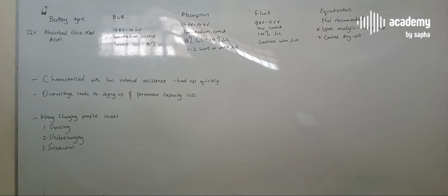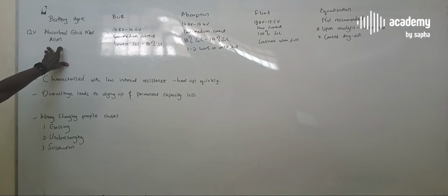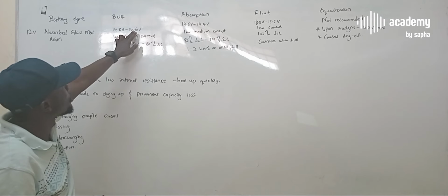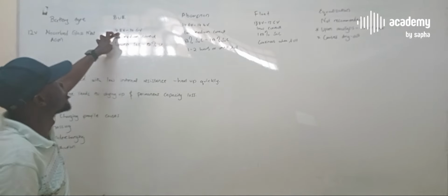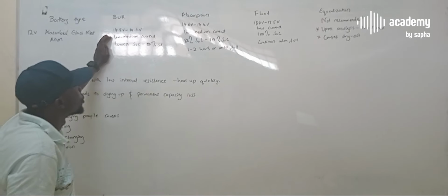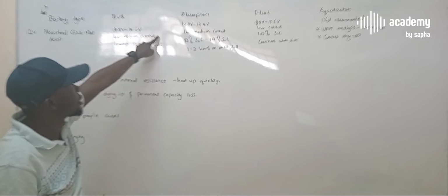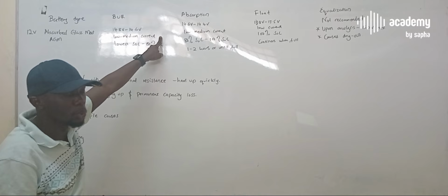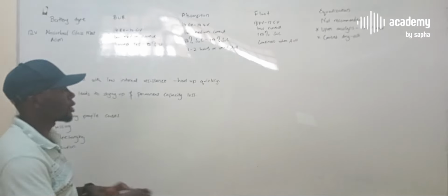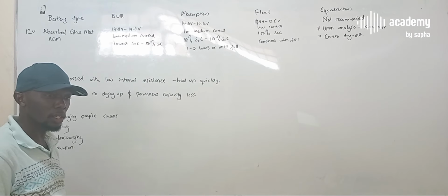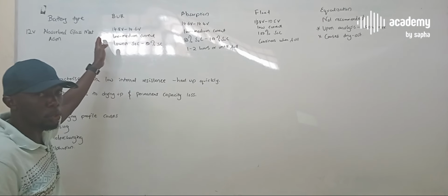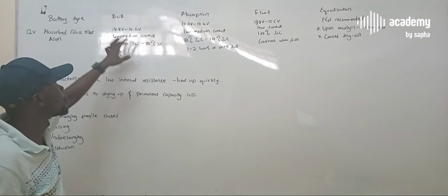So the second type of battery is the absorbed glass mat battery, commonly known as the AGM battery. For a 12-volt system, at the bulk stage, we can push between 14.6 to a maximum of 14.8 volts at a very low to medium current. You get these current settings from the manufacturer's specifications, because depending on how they've packed their battery and the internal architecture, they'll tell you what current to use. It's normally medium to low, never the full charge current for these particular batteries.